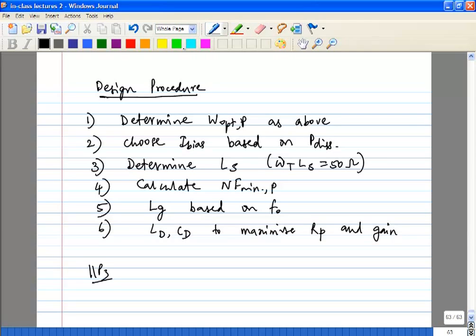Yes, so that is common mode noise. So far we have not talked about common mode noise. We have not talked about supply noise. We have not talked about ground noise. Nothing. We have talked about intrinsic sources of noise. You are right. If you have a case where your substrate is very noisy, your supply is very noisy, in cases like that, you might want to choose differential topologies if it is absolutely necessary.